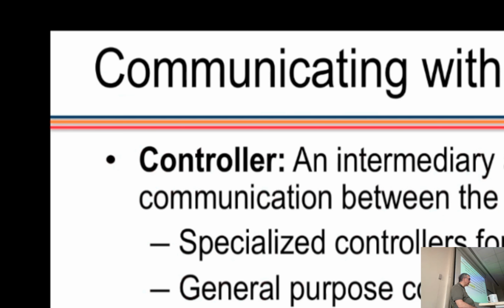We call them controllers. Some communication is done through the ports. Some communication is done through memory. When you write to the memory, it might mean some output. Or you may have special instructions, say write out instructions. You need to call that instruction that specifically writes to the ports. So that is port-based communication or memory-mapped communication.